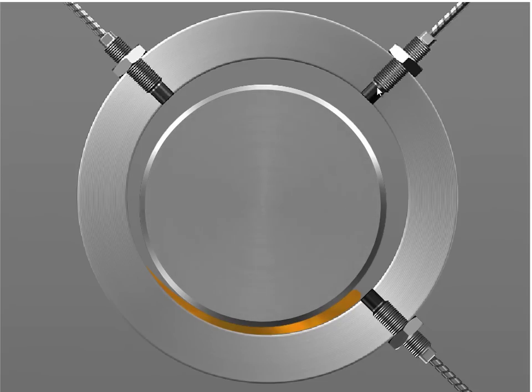So we use these proximity probes instead. These two probes are sensitive to the distance between the tip and the shaft. So as it moves in this sort of direction, this one picks it up, moves in that direction, this one picks it up. The fact is we use it to triangulate. These two probes are mounted 90 degrees apart, and we kind of triangulate the motion of the center of the shaft. I'll explain that a bit more in a second.